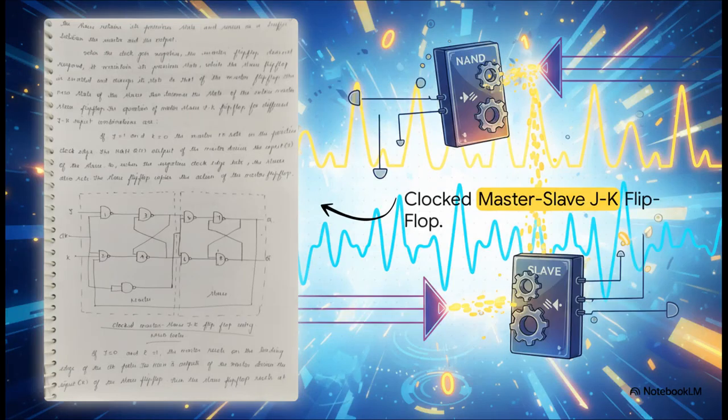The elegant solution to this timing crisis is the master-slave configuration. Built using NAND gates, it essentially chains two flip-flops together. The first one, the master, catches the input data on the positive rising edge of the clock pulse. But the slave flip-flop is inverted. It completely ignores the master until the negative falling edge of the clock. By having the master safely hand the data to the slave sequentially like that, we completely neutralize the race-around glitch.